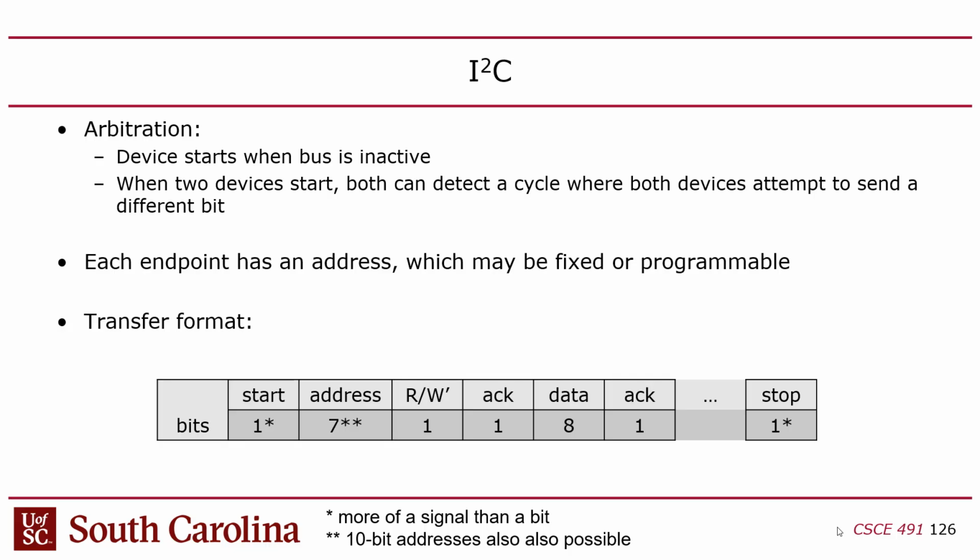Now, the weird thing about this is that if I'm doing a read, then the slave has to send the data that I want to read, right? Which means that the control of the data line has to change again back to... it doesn't change. It stays, scratch that. In the case of a read, the slave keeps control of the data line so it can send the word that you want to read back, right? And then as the master, I have to acknowledge that, which means there's another change of control.